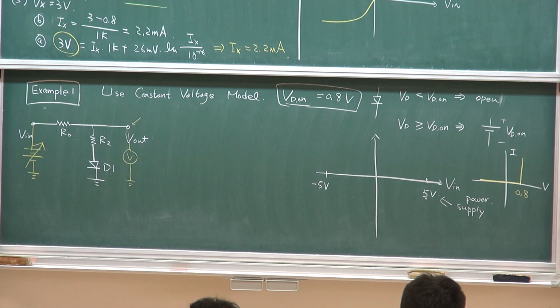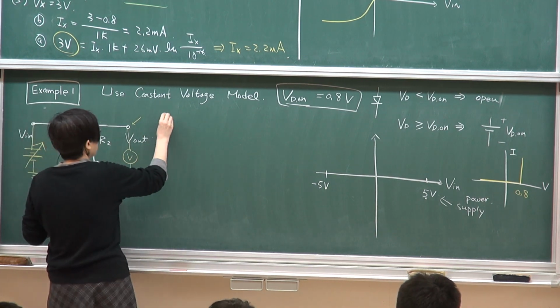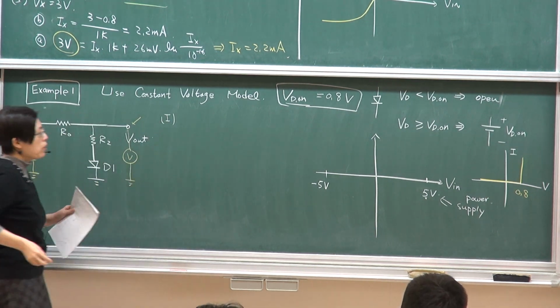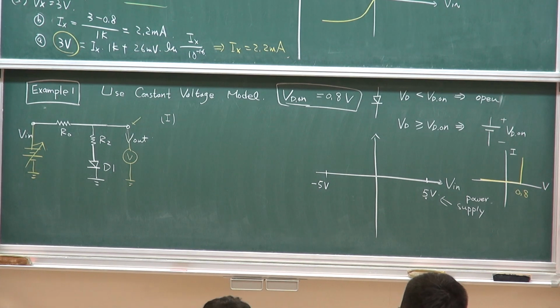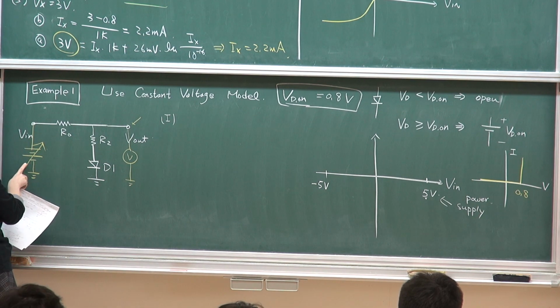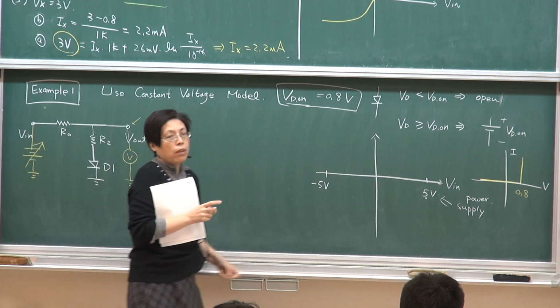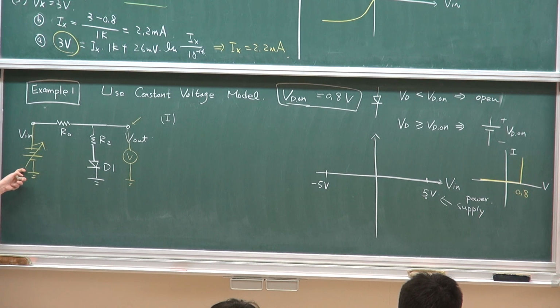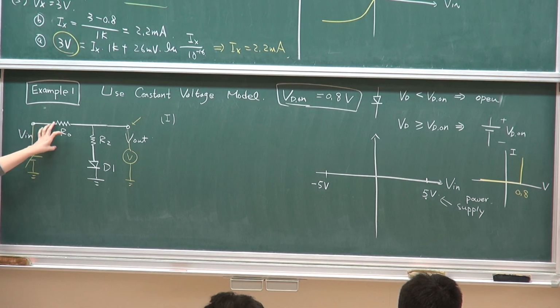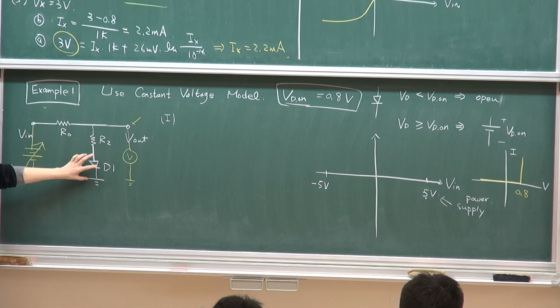So how does one determine what happens? A good way of approaching this type of question is to start with the easy part, where the diode is open, meaning there's no current. So if I start ramping the voltage from -5, this voltage propagates to here and the device is turned off.